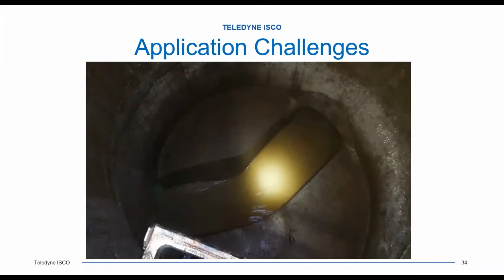Here's another one that's always difficult, which is coming around a bend. This particular one isn't horrible. I've seen way, way worse. But in this case, what they were able to do is mount a remote ultrasonic right over the pipe coming into that manhole. And then the laser could be mounted backward, a little ways from that opening. And now they're reading exactly the same point. So even with the bend in the pipe, they're able to use the laser for that.